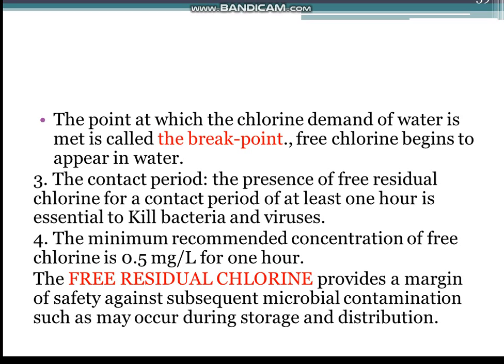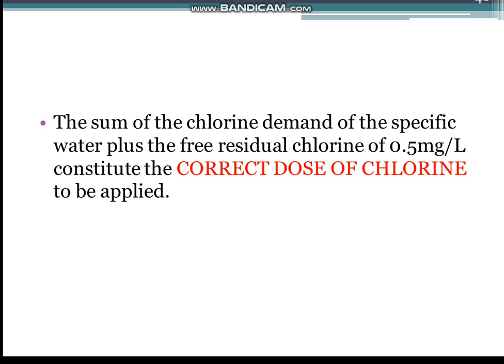Third, the contact period. The presence of free residual chlorine for a contact period of at least 1 hour is essential to kill bacteria and viruses. Fourth, the minimum recommended concentration of free chlorine is 0.5 milligrams per liter for 1 hour. The free residual chlorine provides a margin of safety against subsequent microbial contamination such as may occur during storage and distribution. Fifth, the sum of the chlorine demand of the specific water plus the free residual chlorine of 0.5 milligrams per liter constitutes the correct dose of chlorine to be applied.